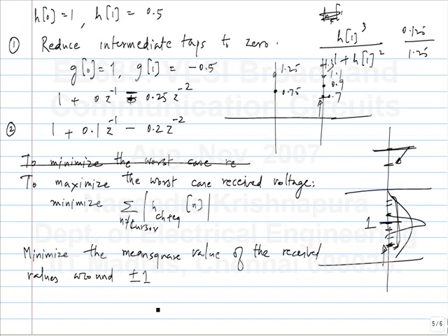Any questions on this? Yeah, that's correct. So if you know the channel response, you can calculate it beforehand and preset the equalizer taps. If you don't know the channel response but know the possible ranges, at least that you should know, right? It will not be completely arbitrary.